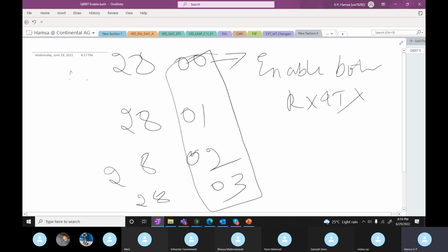If the ECU provides a positive response, what would the positive response be? If you request this, what is the DLC for this? The positive response is 68 00.